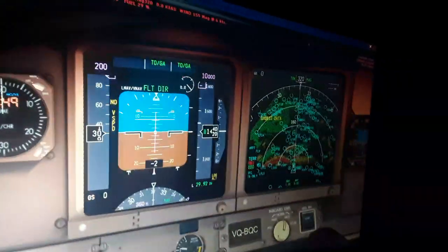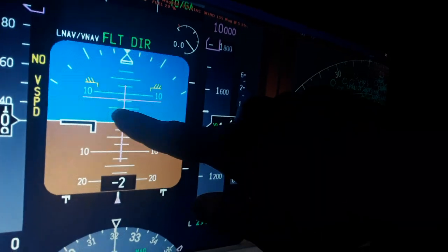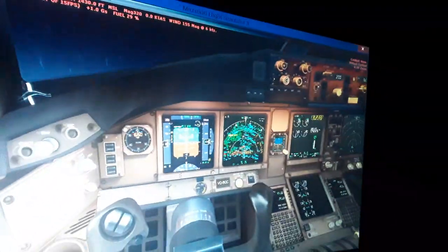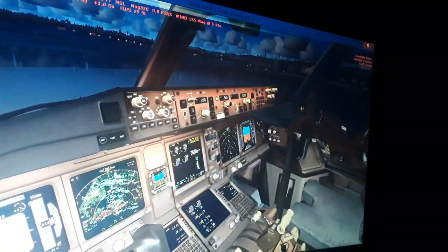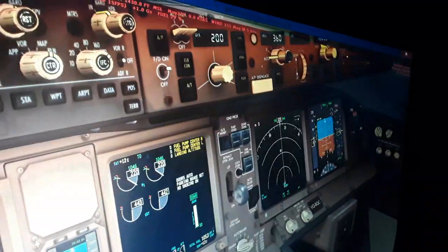So you know if the aircraft climbs or descends by looking at this needle here, not actually the pitch ladder, because it might be confusing for you. The aircraft might be pitching up and actually descending, so you have to know the rate of climb and descent.